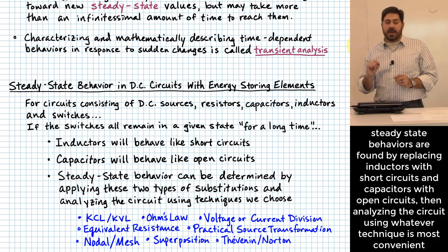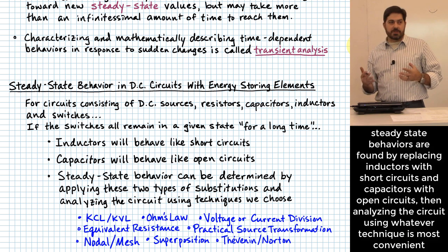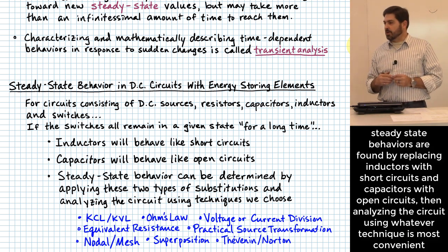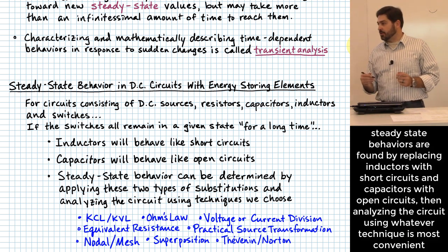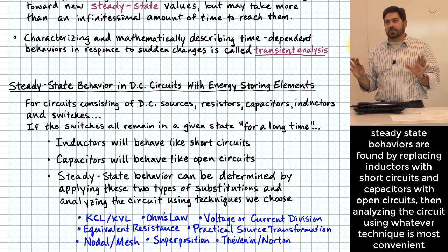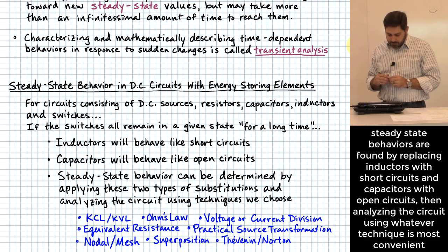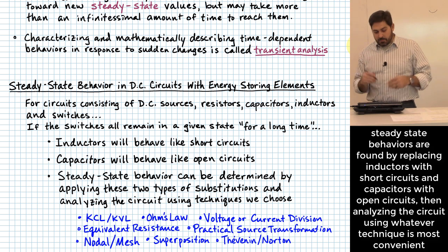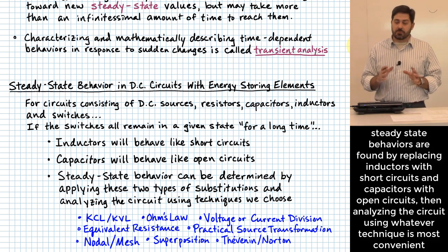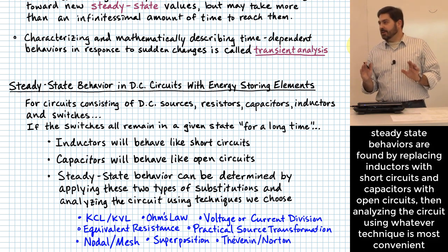Last note I'm going to make on that is we are assuming, both for the inductors and the capacitors I'm going to get to in just a second, that they are ideal. In other words, we're not dealing with the fact that a lot of real inductors also bring along with them some amount of resistance. For now, we're going to treat it as though we can somehow get an ideal inductor. All right? For capacitors, if you leave them connected for a long period of time into a circuit where there's no changes going on, they will begin to behave like open circuits.